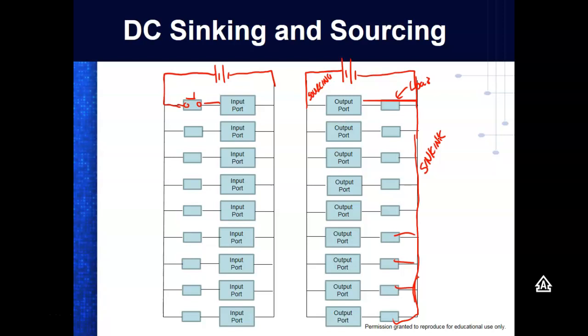The red line, we got a meter. This guy here, so this PLC, we say it's AC, so it powers up AC. It's got its own power supply, and then DC would define what we have on our inputs, and then this has relay outputs.